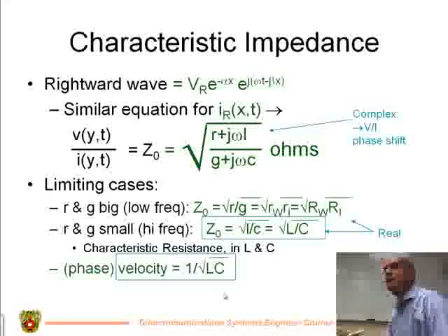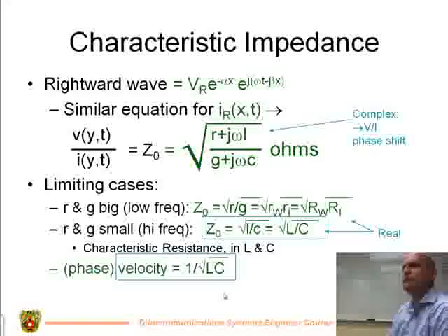Yeah. Okay, so what we're saying, and this makes sense if you just think about it in general terms. At DC, the inductance and capacitance have no effect because they're based on change in current, right? And at really high frequencies, almost all the effect comes from the inductance and capacitance because we're changing current all the time, so the resistance has a very small effect compared to that. Does that make a little more sense?